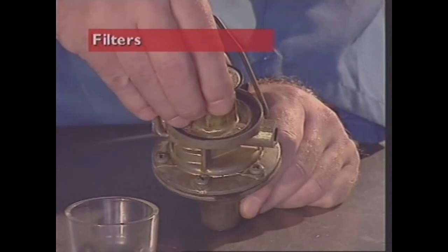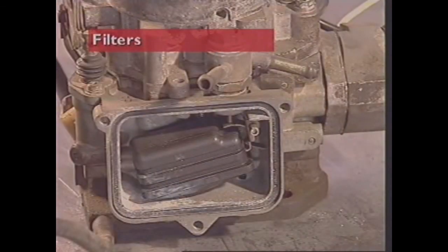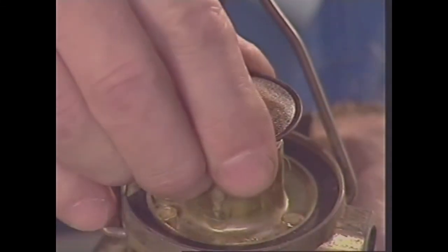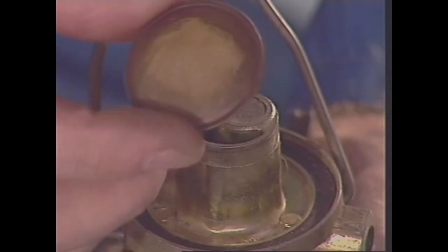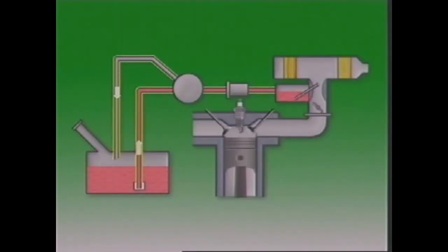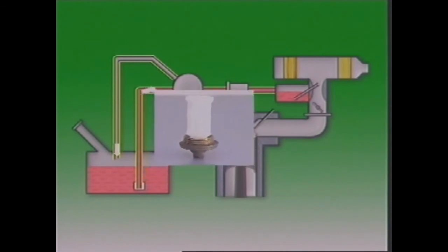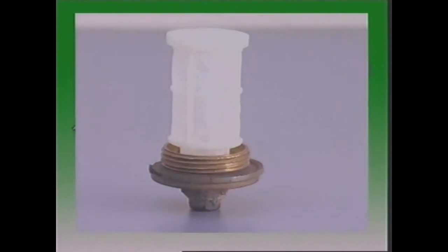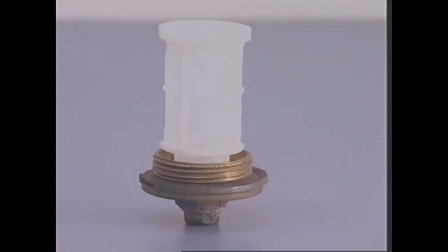This section examines filters for carburetted engines. Fuel must be kept clean, or the jets in the carburetor could be blocked or corrosion can occur. So fuel systems always contain filters. In this carburetted system, a fine filter of nylon or gauze is fitted to the pickup pipe in this petrol tank. A large surface area is provided to allow adequate flow rate and better filtering.